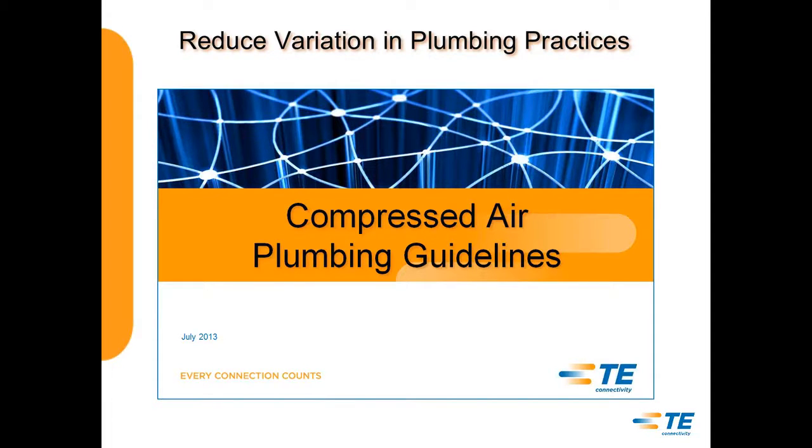One of the things we continue to see is interchanging metric and standard fittings together. We've got a whole lot of equipment that uses both of those. We're probably half and half. We've got a lot of metric tubing and a lot of standard tubing. If you don't pay attention to those, even though it feels like it snugs up pretty good, it will leak. So we continuously find air leaks that are ultimately the fault of having metric and standard fittings components put together.